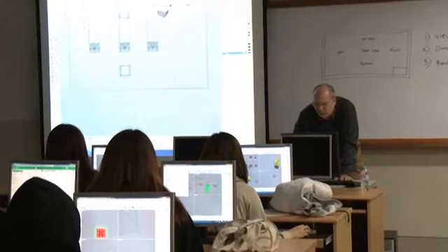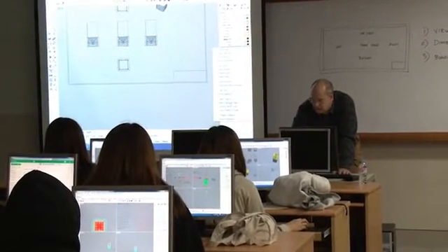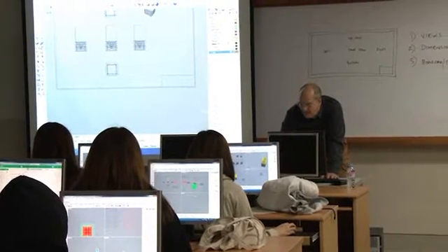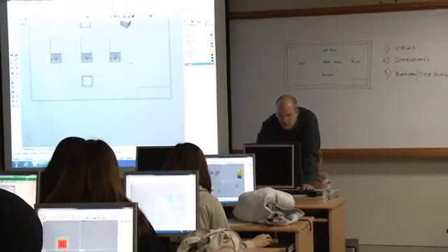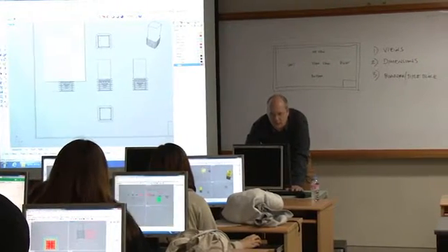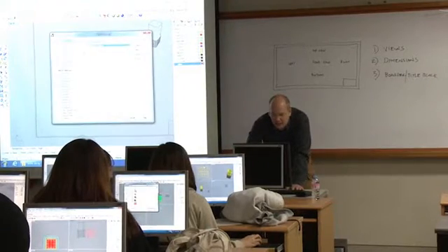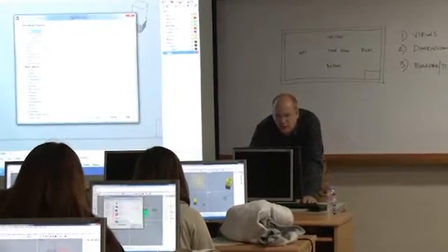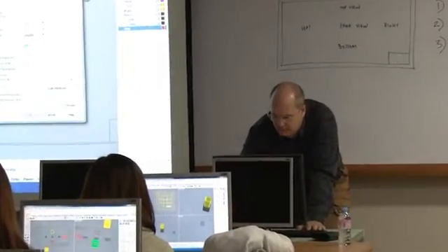Okay, but wrong layer. Change there. Okay, now my text is a little bit too small, hard to read. So let's go into our dimension styles, and let's make a few changes here to our text height. Let's change it to 20. There we go, that's readable. Okay, I like that. This is another important dimension right here.